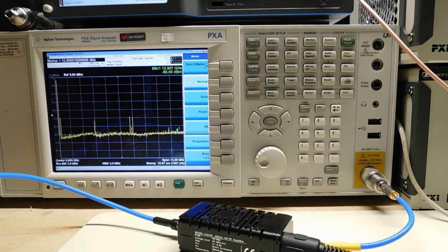This of course is a useful way of improving the fidelity of a baseband signal, but what I really want to do is generate signals directly to RF with my arbitrary waveform generator, so I don't have to bother with IQ modulators or IF mixers and local oscillators. So I'm going to build a new waveform now, which is an IQ waveform, so it doesn't contain just magnitude points like my previous waveform. I'm going to download that to the instrument. It looks distorted now because the instrument is still expecting magnitude only. I'm going to put 8x interpolation on, still looks distorted. And now finally I'm going to turn on the digital up converter of the Proteus arbitrary waveform generator.